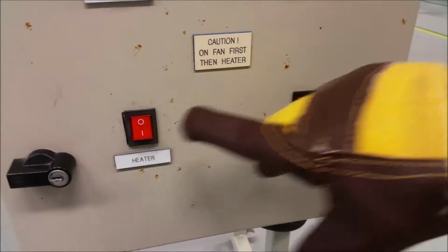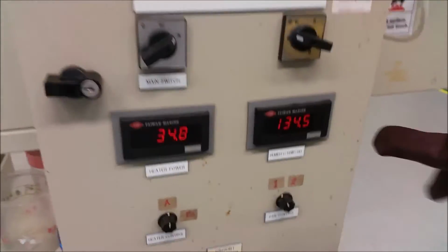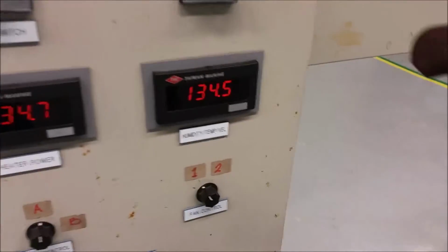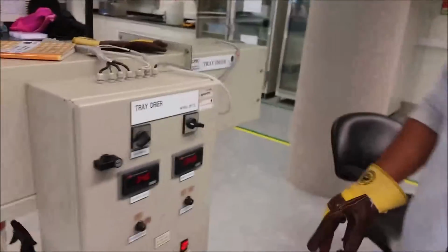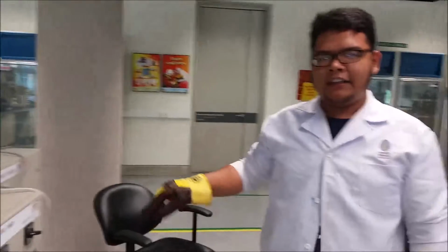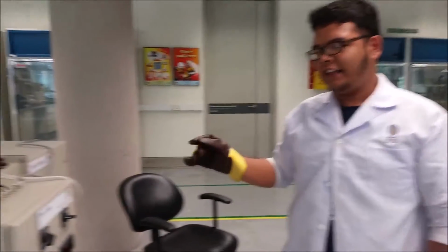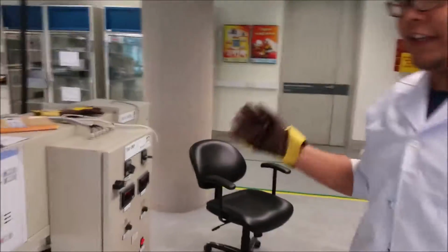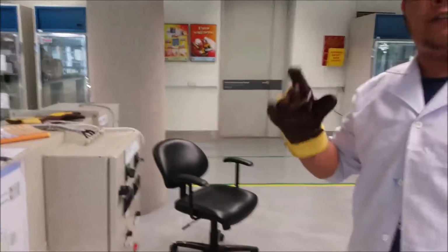And then we need to turn on the fan first before the heater. Okay, turn on. And then start taking the initial reading of H1, H2, T1, T2 and velocity. And then the reading of the temperature and humidity will be taken every 30 seconds until the drying finishes, which we can see from the mass of the sand, which will turn into the initial mass. That's all for the experiment part A1.